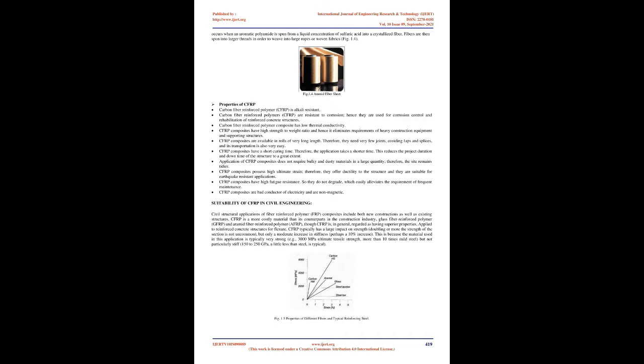When an FRP specimen is tested in axial tension, the applied force per unit cross-sectional area, stress, is proportional to the ratio of change in a specimen's length to its original length, strain. When the applied load is removed, FRP returns to its original shape or length. In other words, FRP responds linear elastically to axial stress. The first application of FRP strengthening was made to reinforce the concrete beams.